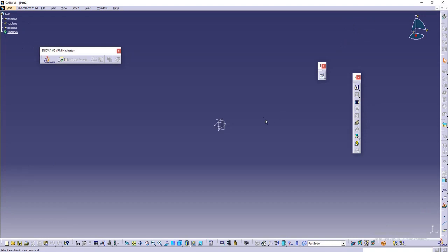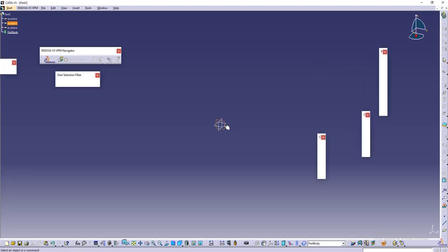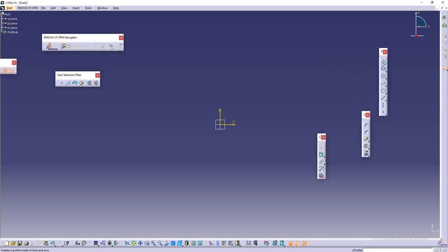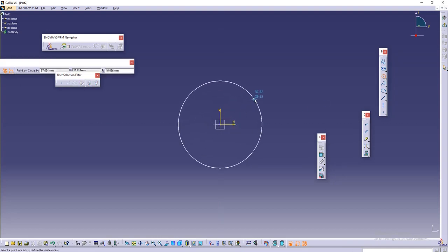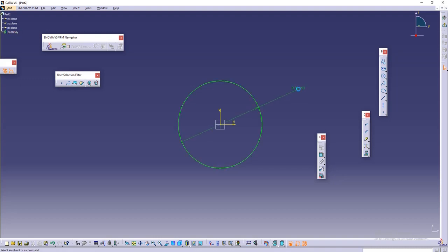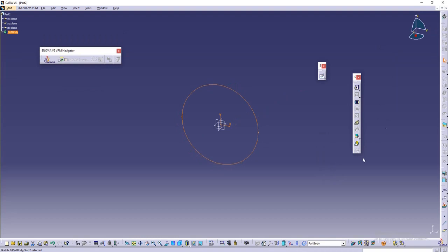So here you just go to the sketch, select the plane, and then if I have to create a circle, what I will do, I'll create the circle. What is the next step? Next step will be the dimension 92. Then what I have to do, exit the workbench. Now the circle is here, a single sketch which is closed. Even if there is a single line outside, it will not convert into the solid thing, right?